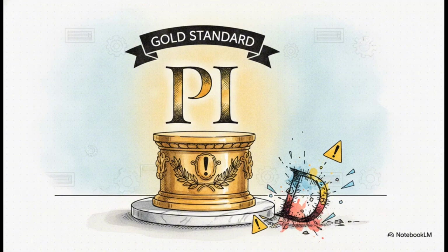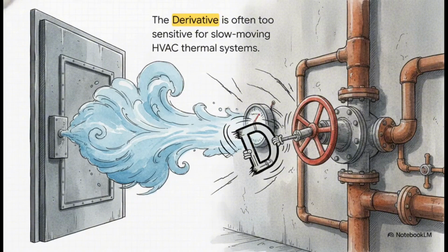Full PID can honestly be incredibly twitchy and overly sensitive. PI control just completely drops that derivative calculation, relying entirely on the proportional and integral actions. In our industry, PI is absolutely the gold standard. But you might be wondering, why drop the D? The simple truth is, the derivative is just way too sensitive for slow-moving HVAC thermal systems.